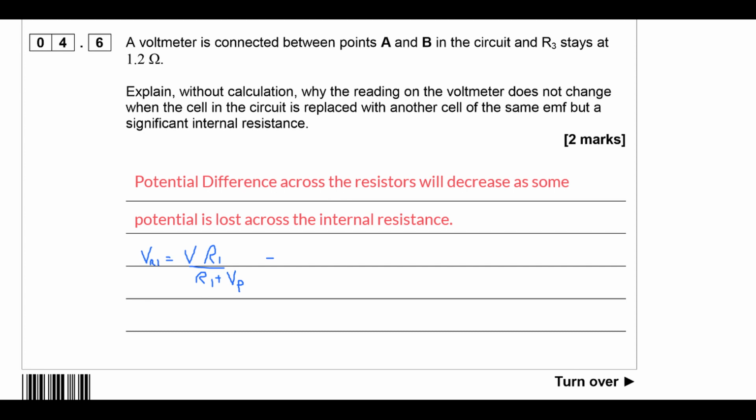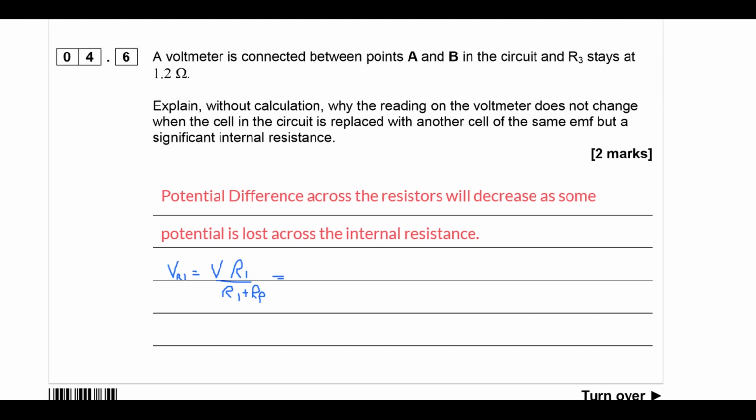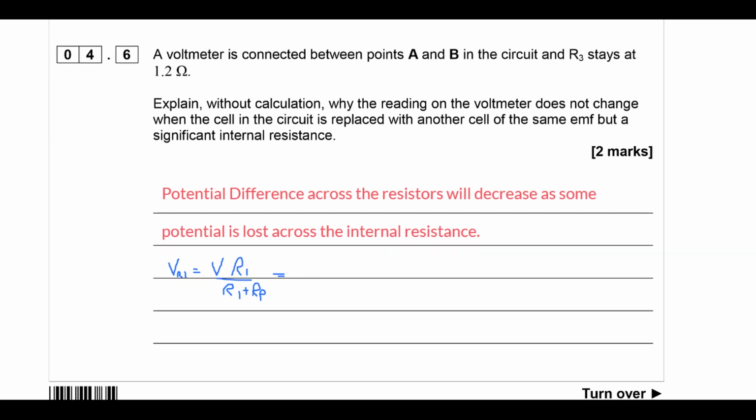Potential difference across the probe? What utter nonsense. The resistance of the probe. So let's calculate that ratio. That's going to be 2.4 divided by 2.4 plus our answer from the previous part, which is 0.95 times whatever the terminal voltage is.